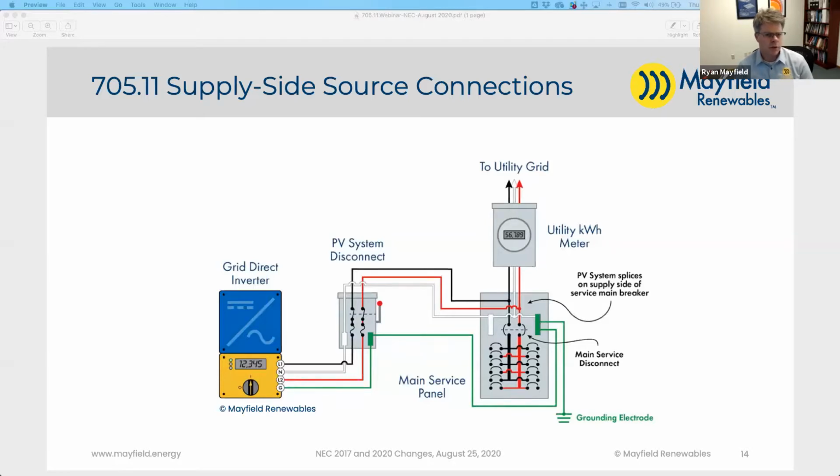I'm not familiar with the modeling end of it, but I have seen the issue come up when we've got a PV switchboard with a lot of circuit breakers coming into it. We're worried about how much heat buildup. And so one thing we've done is just bumped the breaker size up a size, which does mean you're bumping the wire size up to make sure it's good for that higher rating.